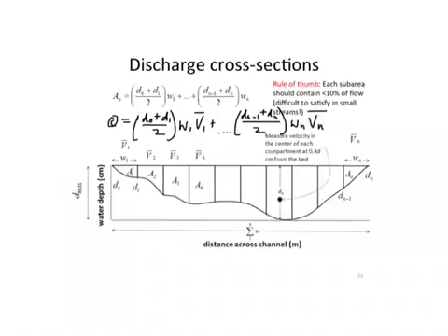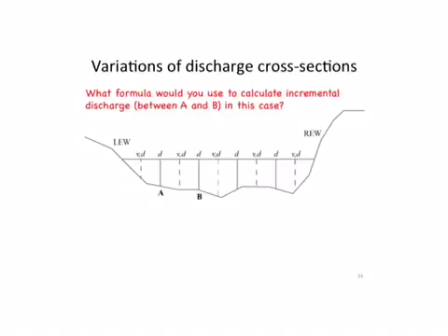Okay? Turns out, though, that this way of measuring discharge is a little bit cumbersome because it requires you to measure channel depth at each of these lines, but then measure velocity in the middle. In practice, it's a lot more convenient for us to measure depth at the same points along the stream where we're measuring velocity, and this is in fact in Strawberry Creek.